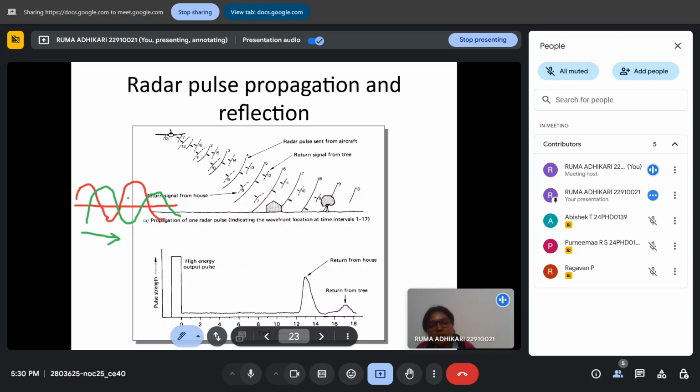So what the matched filter does: after all, we have to detect how the reflected signal has some property from hitting the target. It gets changed, but where it gets changed, to understand that, in layman's language, the matched filter creates a copy of the transmitted energy, and it overlaps and matches it with the received signal.